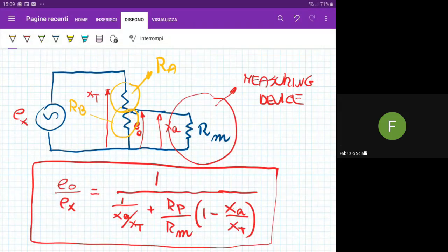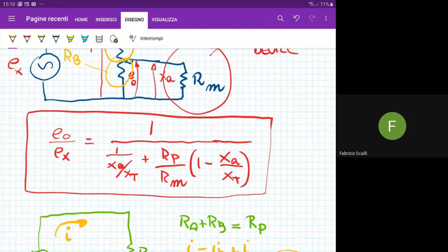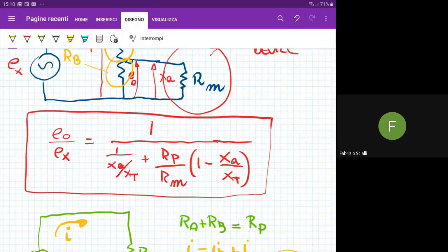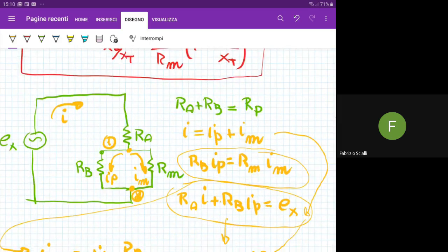The important point is that you can melt everything. Why? Because if you are feeding your electrical circuit with an increased input tension, then you have also to think that, because of the Joule effect, there is heat coming out from your electrical resistance. Okay, so you have to take this into account. How can you take it into account? Just by rewriting this equation, taking into account the maximum power that could be dissipated in your electrical circuit, so that you are not exceeding the maximum power and not melting anything thanks to the Joule effect.